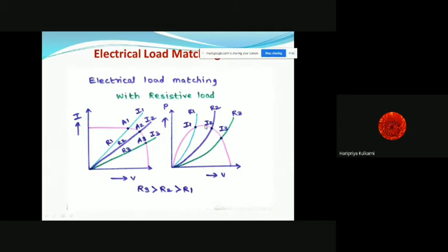Generally, here we get the maximum power. So likewise, when we install a particular system, we should first observe the IV and PV characteristics. We should simulate the IV and PV characteristics and decide the point of operation. Ideally, we should keep the load on the system in such a way that it operates in the middle zone of the PV characteristics so as to extract the maximum power.